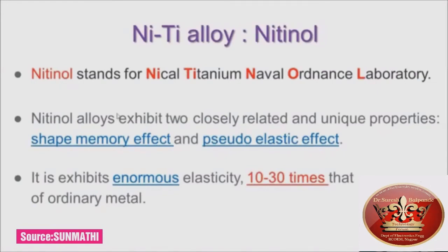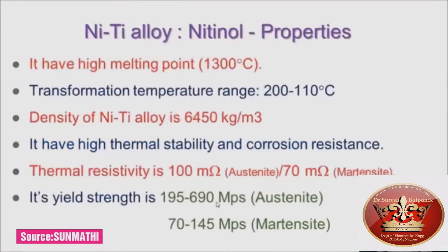Nickel titanium alloy, or Nitinol. Nitinol stands for Nickel Titanium Naval Ordnance Laboratory. The alloy exhibits two closely related and unique properties: one is the shape memory effect and the other is the pseudo-elastic effect. The shape memory effect is completely dependent on temperature, and the pseudo-elastic effect is completely dependent on load or stress value. One is a temperature-induced process and the other is a stress or load-induced process. It exhibits enormous elasticity, nearly 10 to 30 times that of ordinary materials.